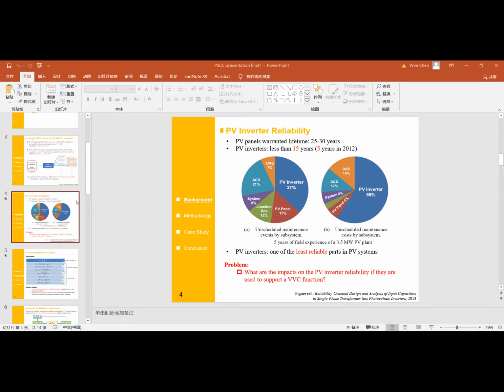But the point is to use the reactive power to complement the active power's fluctuation. That is because in the inverter lifetime model, the junction temperature fluctuation has much more influence on the lifetime than the mean junction temperature value.